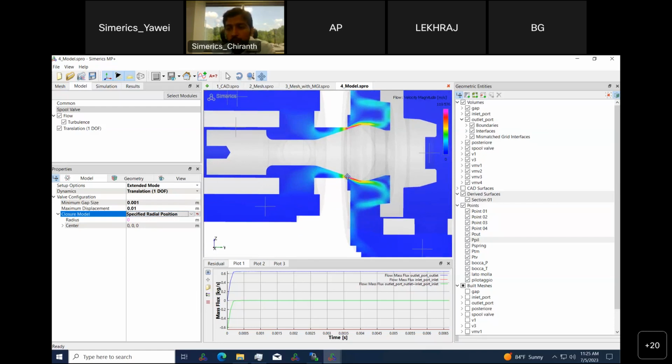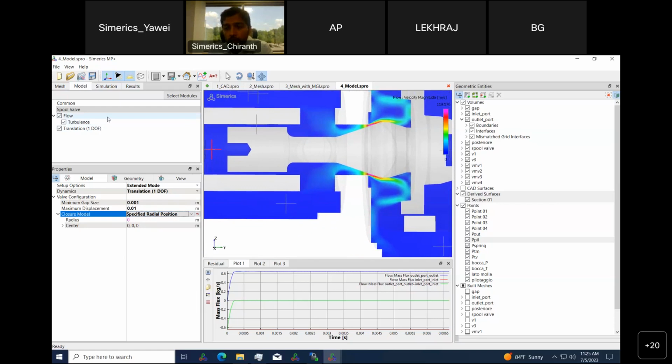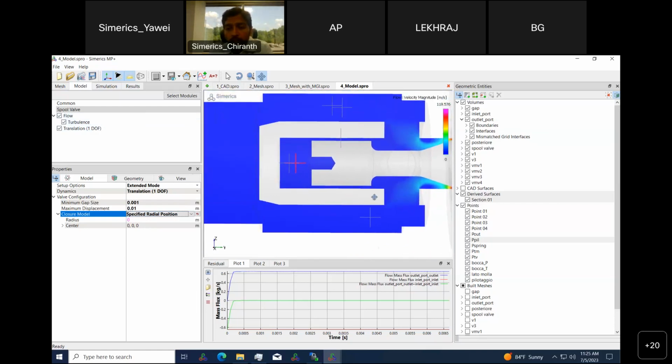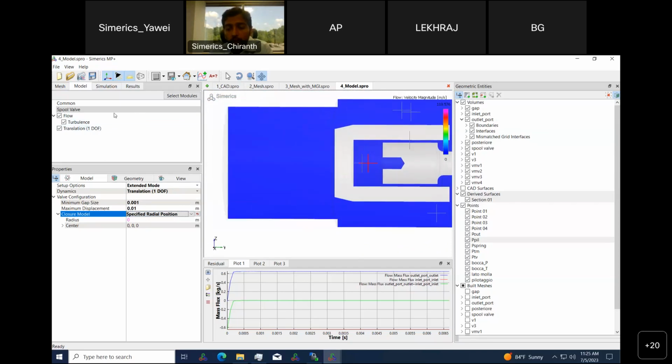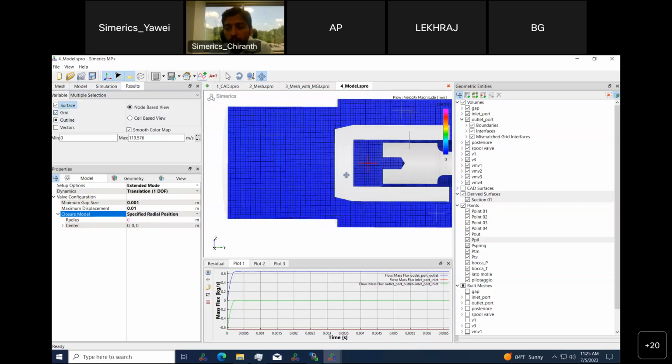So the next question is, can you talk about how you handle the boundary layer flow and what turbulence models are available? In terms of boundary layer flow, I think we have the option to refine the mesh size on the boundary. So you can do a local refinement on the cell size on the boundary. So your cell on the boundary is much finer than the bulk mesh.